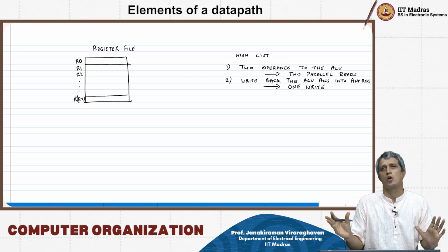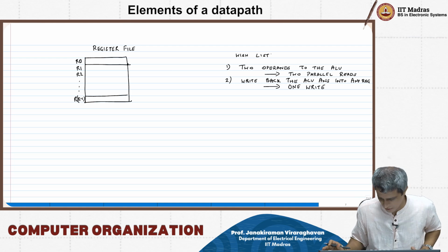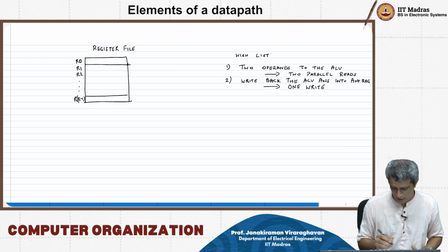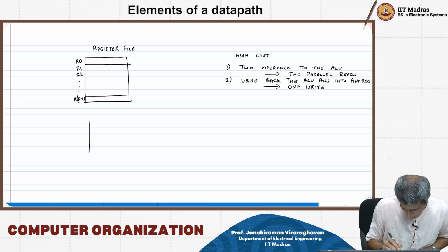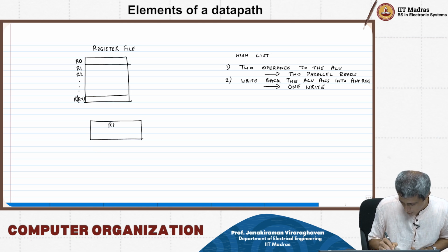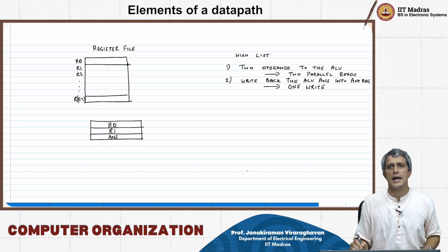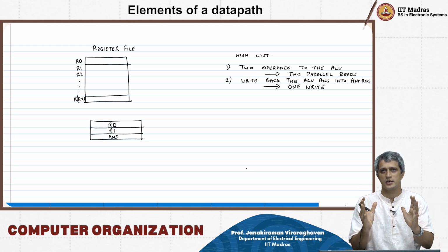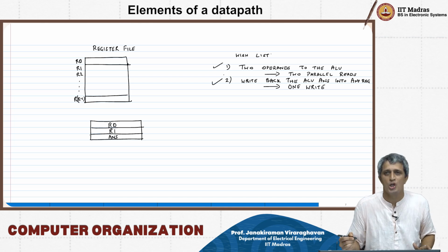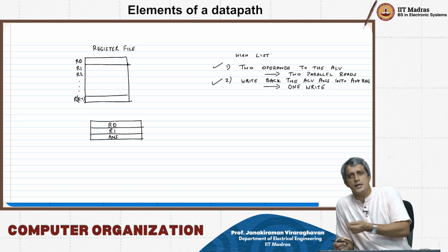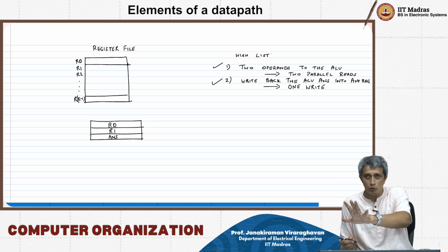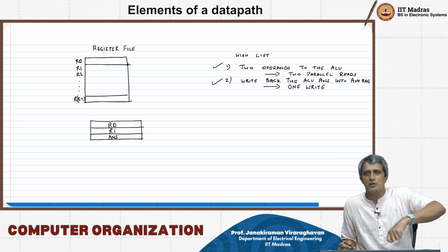Earlier we had hard coded all these to just some fixed operations for these registers. So in the context that we have, what I am saying is, I want to take these three registers R0, R1, answer, and a bunch of three registers with these properties. So I should be able to choose any two of these as arguments to my ALU and write back into any of these.